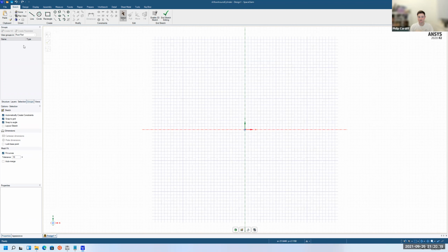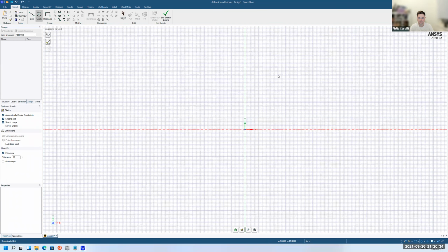We're going to sketch the circle and then the outer bounding box, and then we'll set dimensions on it as we go. So for the circle, we're going to base that on the origin. Click the origin, drag out. You can even type here if you wanted. So 1 meter is going to be the diameter of the cylinder. It's going to take a second to scale out.